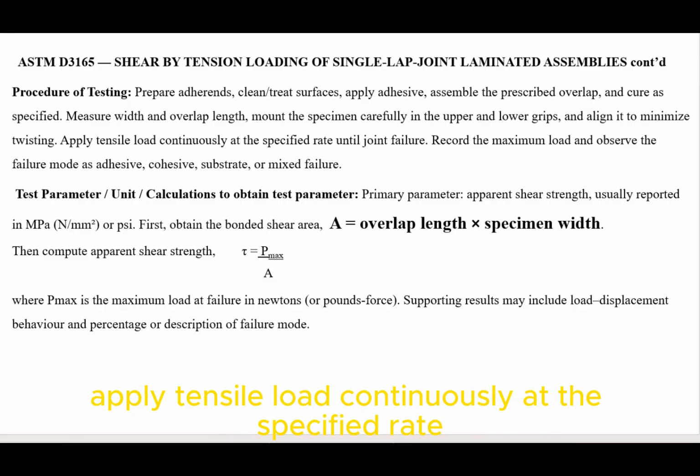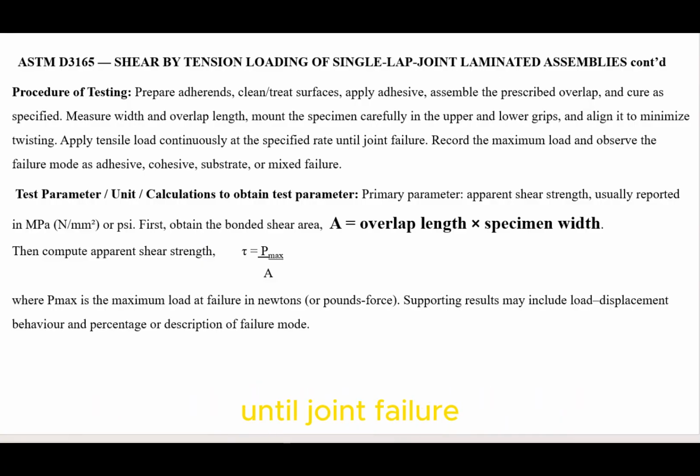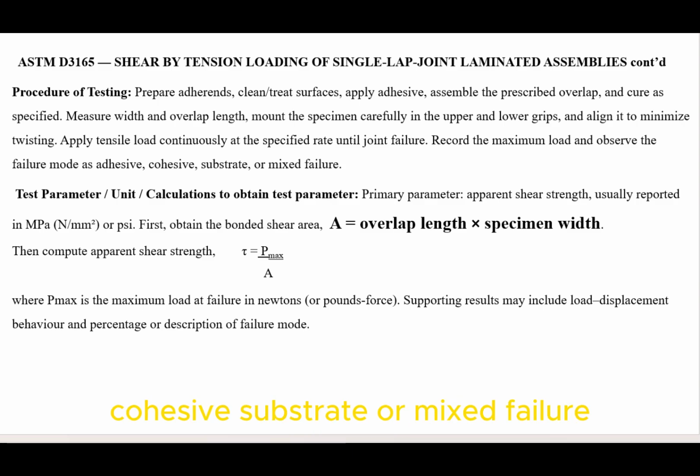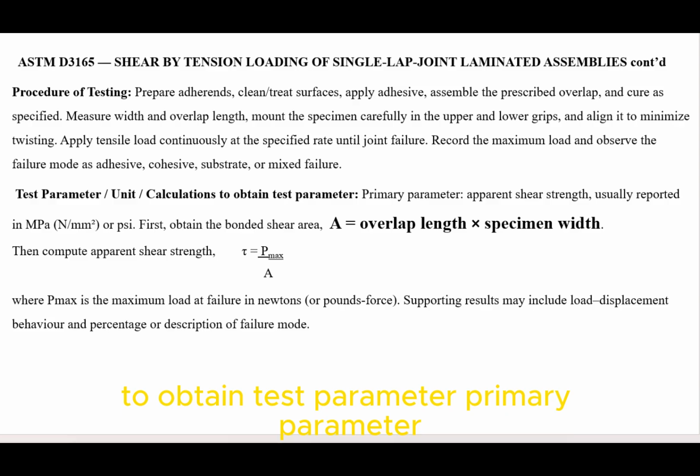Apply tensile load continuously at the specified rate until joint failure. Record the maximum load and observe the failure mode as adhesive, cohesive, substrate, or mixed failure. Test parameter, unit, calculations to obtain test parameter.